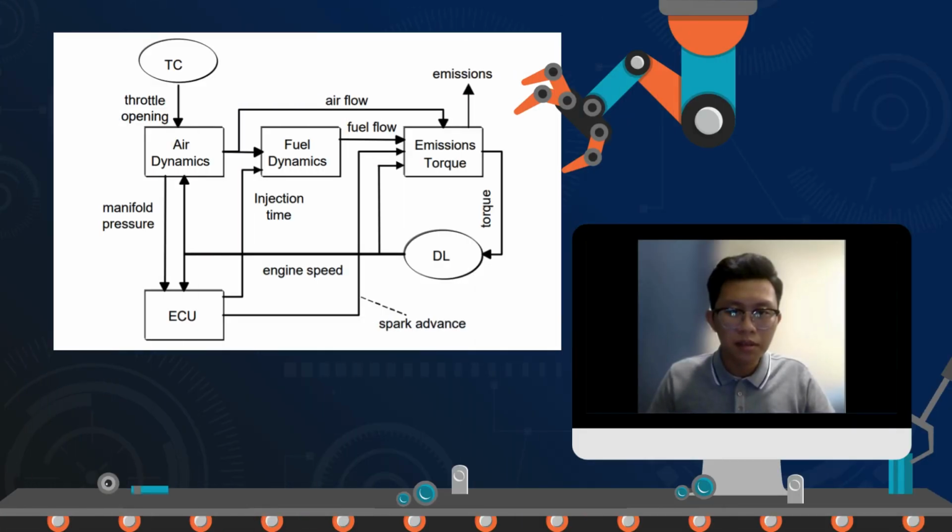In the figure given, a diagram of an engine dynamic model is shown. The main parts consist of the main physically important submodels, such as the engine control unit and the in-cylinder process. There are two dynamic subsystems that make up the intake manifold block, while the fuel dynamic model depicts the effect of fuel wall wetting and evaporation in order to estimate the real port air-fuel ratio, which substantially influences engine torque and emissions. The air dynamic model computes the airflow rate through the throttle body and the engine port.